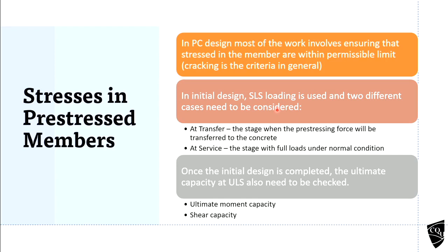Cracking comes under serviceability. Deflection, cracks and everything comes under serviceability. So we are going to use the serviceability limit state, SLS, for our initial design. We did the same for slabs and beams in RC design, so we use a serviceability limit state.